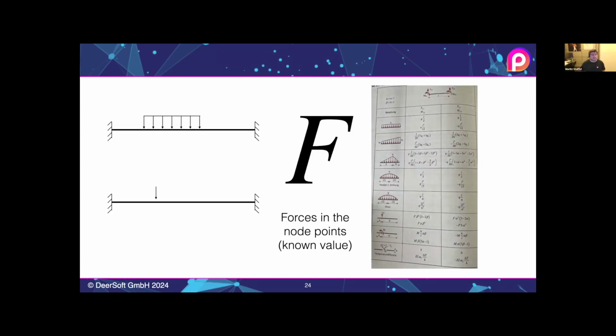The next thing that we need to know is the forces on the end and starting point of the trusses. There are specific tables that define how the forces and moments transfer from the middle to the left and to the right. I've put the most basic formulas in here as well. Again, we don't really care about the individual numbers, just the process.